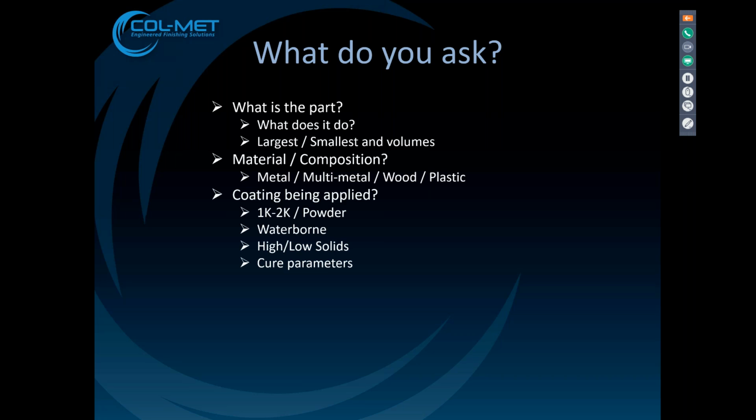And also, what is the coating that we're going to be applying? Is this a liquid line or is it a powder line? What are the coatings consist of? Are they waterborne? Are they high or low solids? And really key is the cure parameters. What do we need to do in order to cure the product so we can handle them for assembly or packaging after the coating?